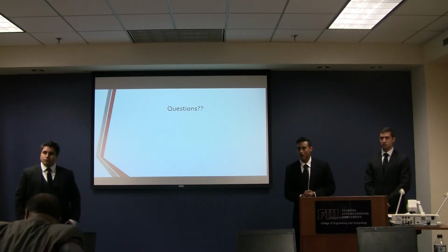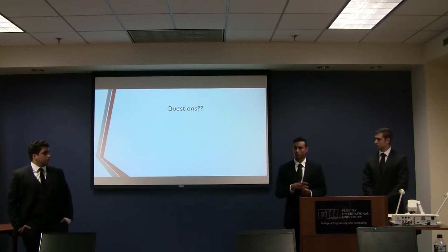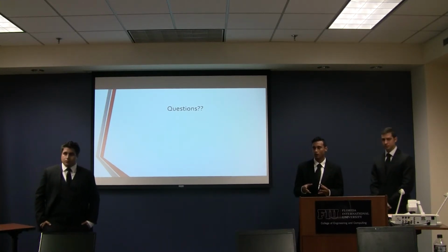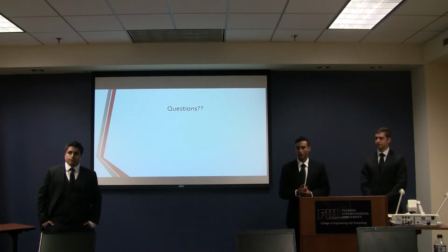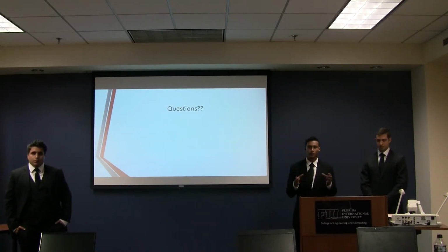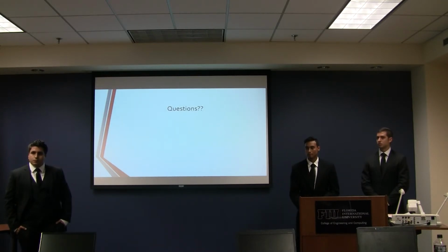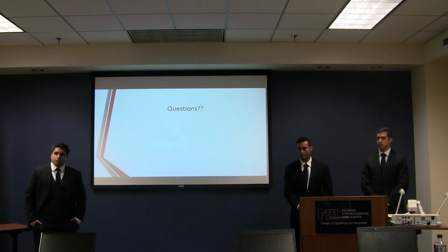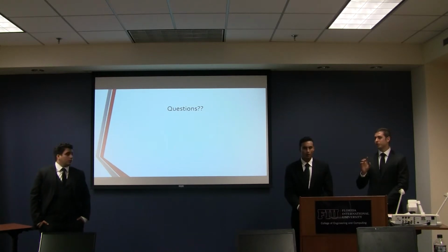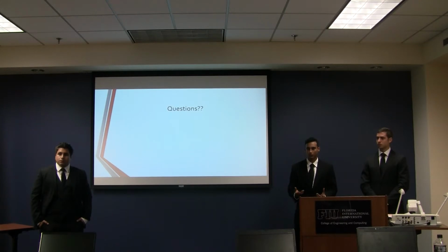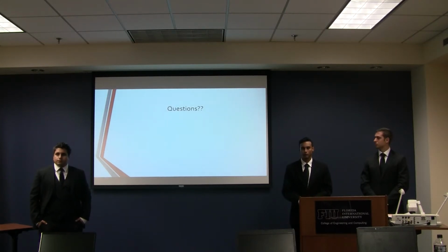As compared to what? As compared to the base turbo, the TD04 turbo compressor. We're using the housing; we're not optimizing our housing. So are you going to have data from the existing turbo and the new turbo? Yes. It's not the complete turbo, it's just the compressor wheel that's going to be the difference in the whole system. We're going to compare the two, and hopefully we can get results that improve our compressor.